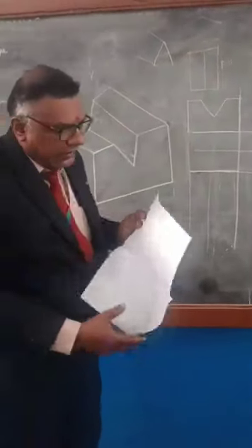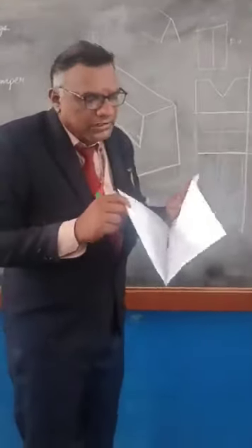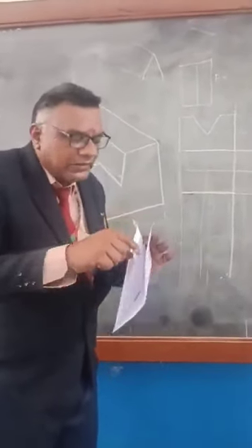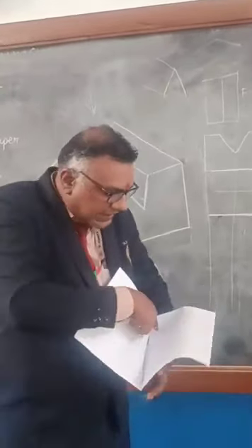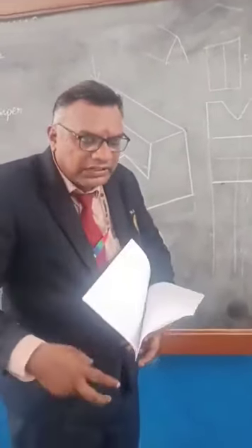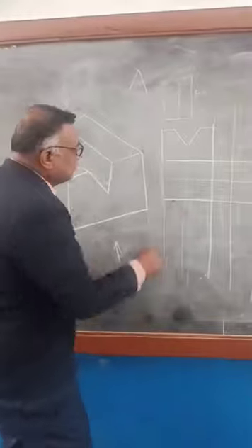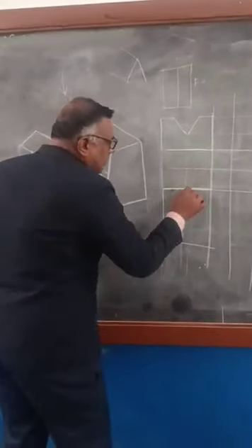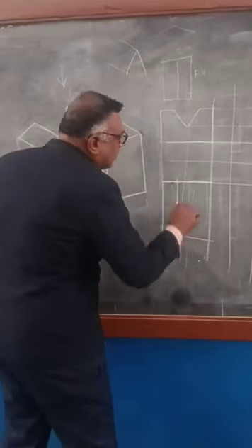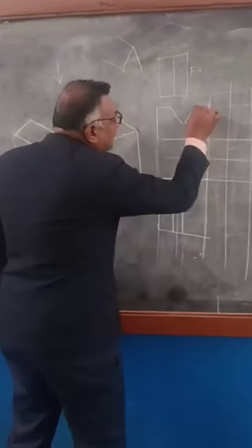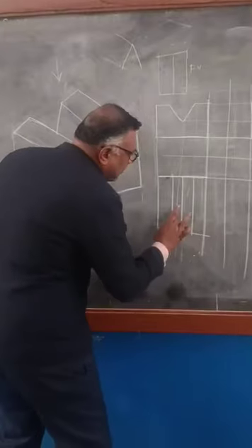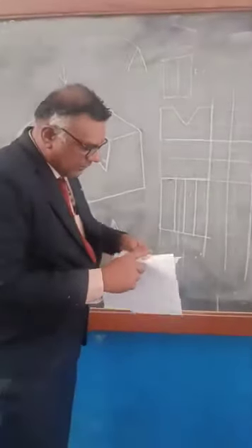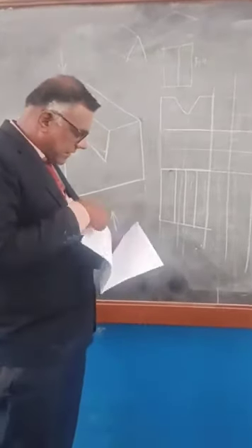Similarly, when you are viewing from this side, in the front view it is a V shape. When you are viewing from the top view, there will be a line. Here there is one line, a center line, and another line. So three lines should be in the top view. So construct your box. One, this center line, another line. Here you can identify this is the first line.